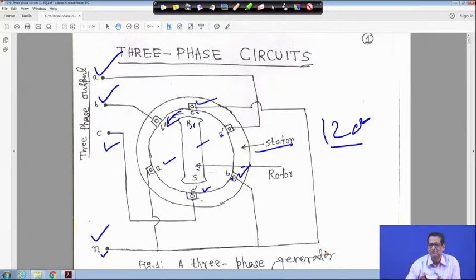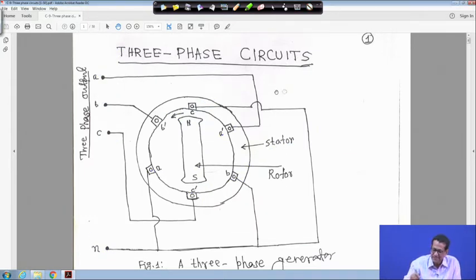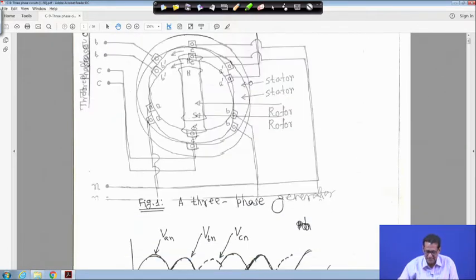The main thing is that the philosophy is different. Just to start the three phase circuit, the rotor is a magnet, suppose it is revolving, and you have windings which are 120 degree apart, right? As the magnet is revolving, the flux links these windings, so voltage will be induced, right? As they are 120 degree apart, how does this happen?